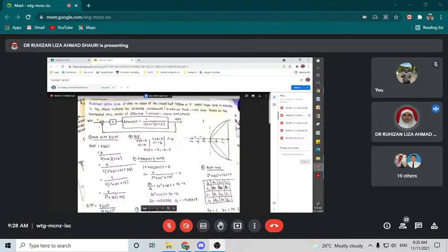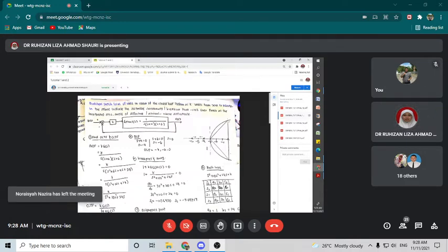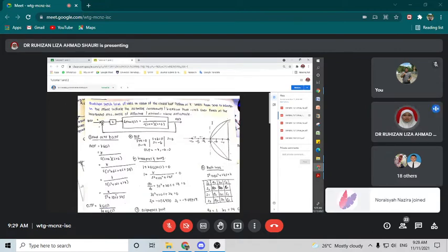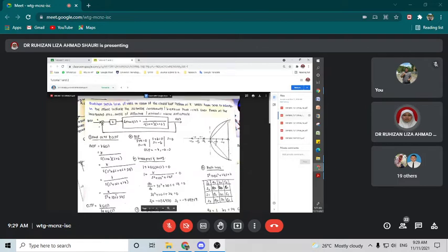As for the arrival, there are no complex conjugate open loop zeros, you don't have it. The same goes for the poles. There are no complex conjugate open loop poles, right? So no need to calculate that. You just work with the real axis and the breakaway.